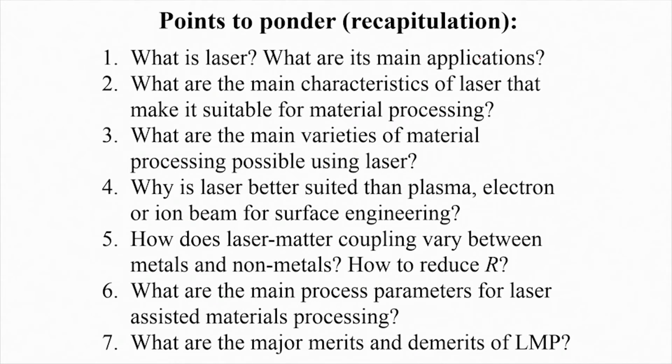The parameters I have already mentioned, and by suitable choice of these parameters, one can do only solid state heating, or allow melting and solidification, or alloying, or one can do various kinds of machining, micro machining, drilling, joining and so on. Everything is good about laser, but the capital cost is very, very high, and you also need a fair amount of skill for the correct use of laser for various materials processing. But on the other hand, the biggest advantage is that it's an extremely fast process.